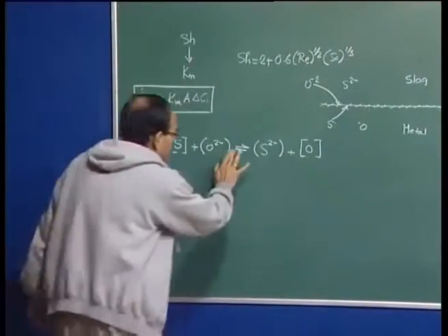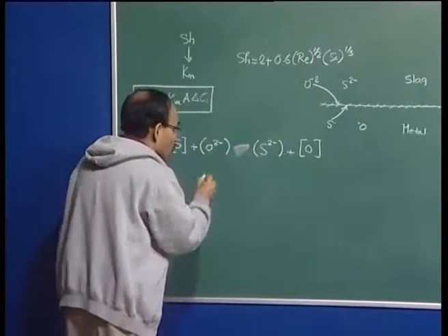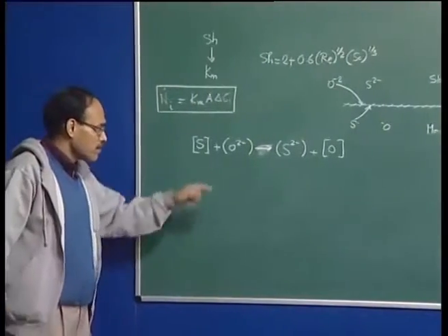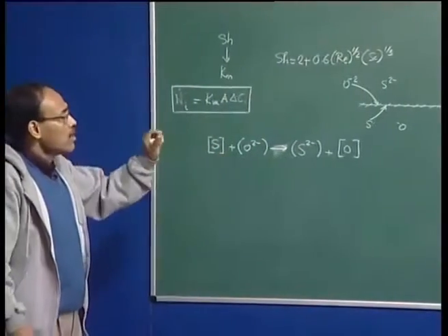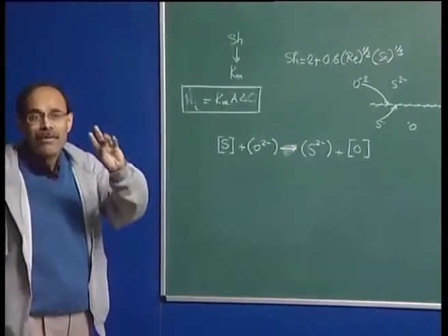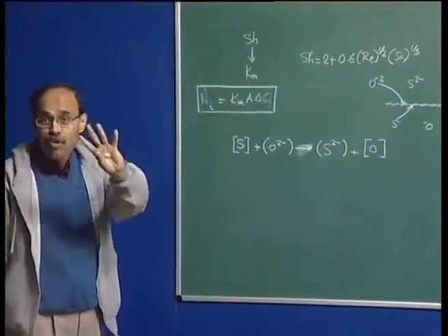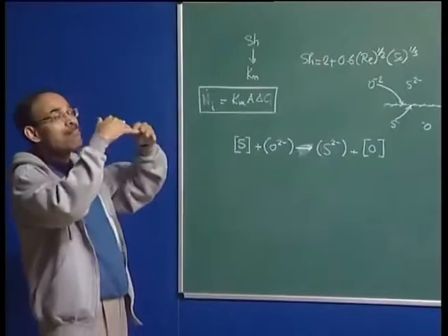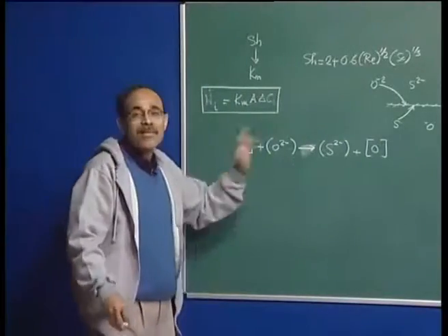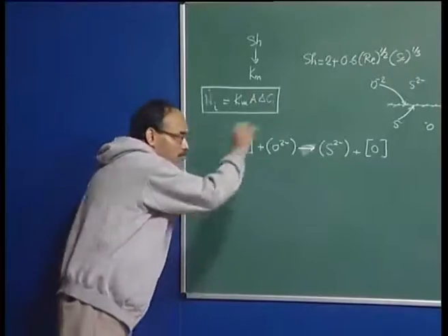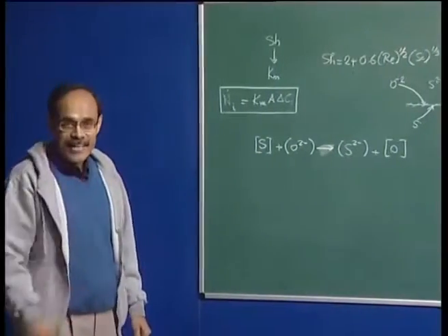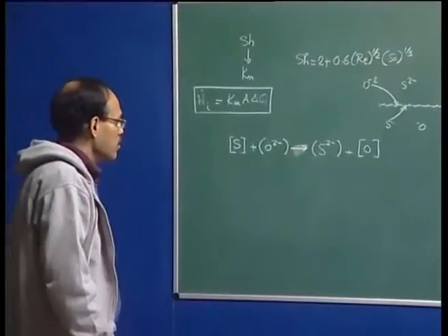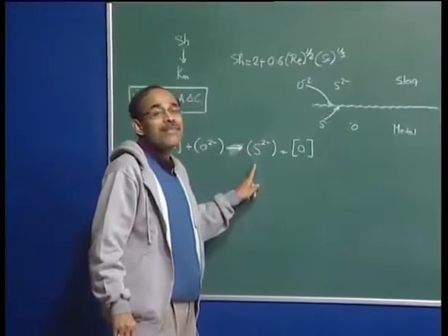So, what we are talking about now is not equilibrium, but continuous transfer of sulfur. The continuous transfer of sulfur, as I have mentioned, is comprised of 5 different kinetic steps, of which 4 are mass transfer, transfer from bulk to the interface or moving from the interface to the bulk, and 1 is the chemical reaction. These are called the individual kinetic steps, and the rate of the desulfurization is going to be a function of the rate of the individual kinetic steps.